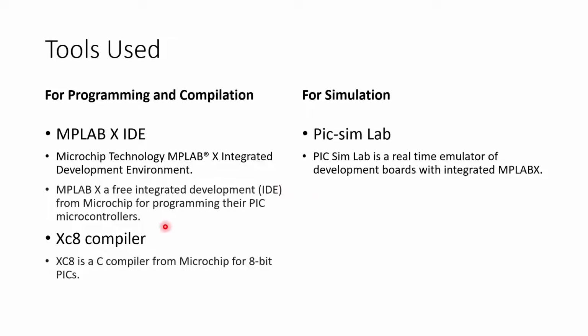For the generation of the hex file, we have used the XC8 compiler, which is a cross compiler from Microchip for 8-bit PICs. Our selected microcontroller is 8-bit, therefore we have to use the XC8 compiler. For simulation purposes, we have used PICsim Lab, which is a real-time emulator of development boards with integrated MPLAB X.